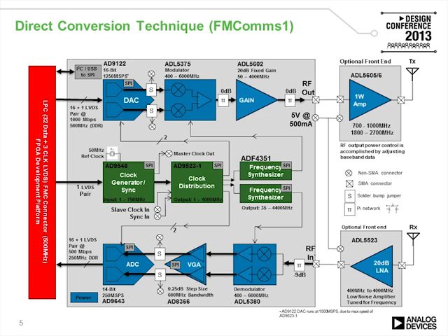The receive path has an optional LNA, demodulator, VGA, and ADC that gives us IQ, which is either fed from the transmit side or received on the receive side from the digital logic inside our FPGA or, like I said before, processing system. As well, on this platform we need clock generators, synchronizers, dejittering devices, distribution, and our LO frequency synthesizers.